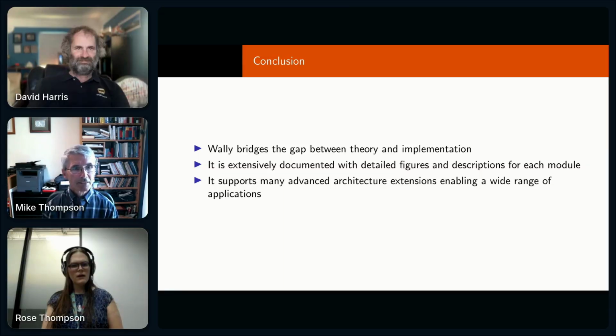So it was at the time this was first written in 2020. It goes against the way we've done all the rest of the logic, and I'd have to revisit the path that interfaced to the reg file. Rez, do you happen to know off the top of your head? I thought the write into the reg file is written on the negative edge, and the read path is asynchronous. Yes, it is. Yeah, that's correct.